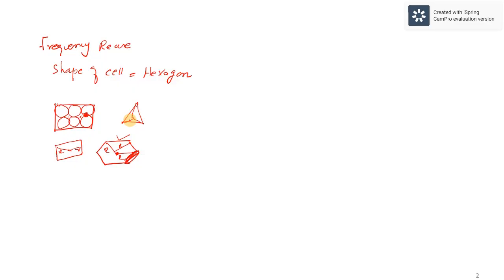When using a hexagonal shaped cell, the base station areas are depicted as either being in the center of the cell, or center excited, or on three edges of the six cell vertices. So that is called an edge excited cell. For center excited cell, omnidirectional antennas are used. For edge excited cell, sectorial directional antennas are used. These different types of antennas will be studied later in this chapter.